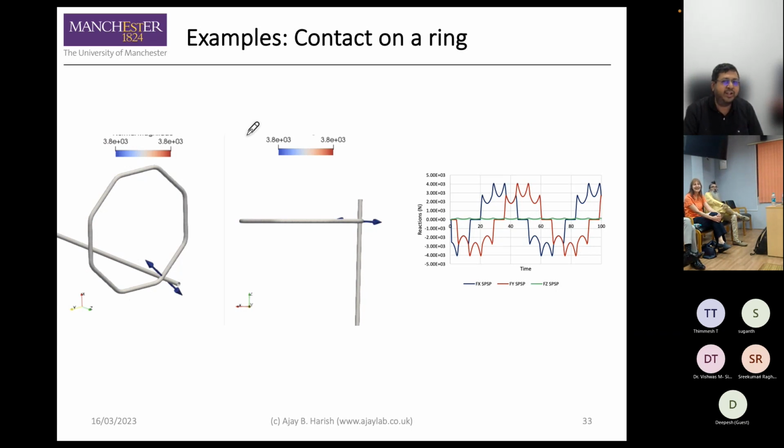Right. So this was basically to test the robustness of our contact algorithm, primarily because the normal is changing, and every time the normal changes, you need to take the variation of that and linearize it. Most algorithms, even commercial software, eliminate this, putting in some stabilization to make everything work. But if you have very large changes in the normal, especially kinks, then the contact algorithms stop working in a way. That's where it fails. So we were just trying to test how robust our algorithm is, what we can do with it, and how we can push its limits.